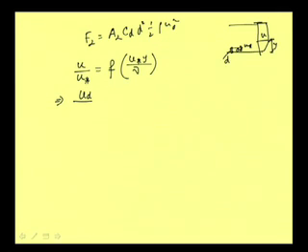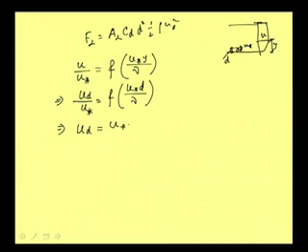So, we will be writing this as UD by U star, and this is a function of, that is why our depth will also be U star d by nu. And then as we said, we do not understand what the value of UD is, or it is difficult to measure. So, we are bringing it in terms of U star times f of U star d by nu. So, UD is a function of the shear Reynolds number, and a product of U star.